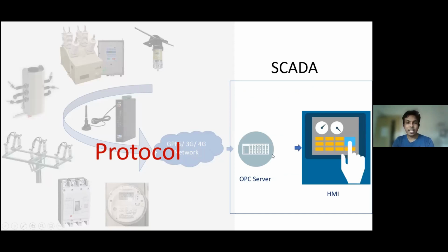To comply with those protocols at the SCADA end, the computer I referred to earlier, we will have another protocol converter. We refer to this as an OPC server. For each and every protocol, we will have not one OPC server but several OPC servers, and what it does is convert each protocol into an open, or OPC, standard, which enables the SCADA software to understand.